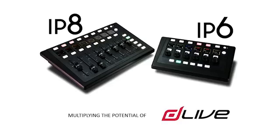They are both soft programmable, which means that you can configure the IP8 or IP6 using a DLive surface, or you can use the Mac or Windows Director software. So you can prepare a configuration even before you connect them live on a system and start configuring and assigning all of the functions and controls before you actually commission an